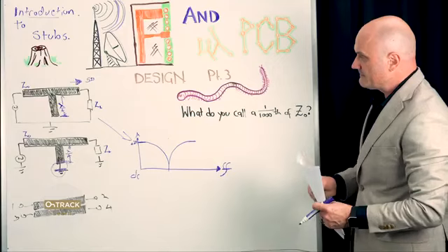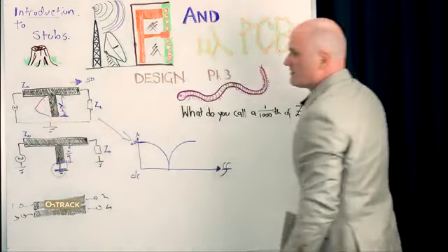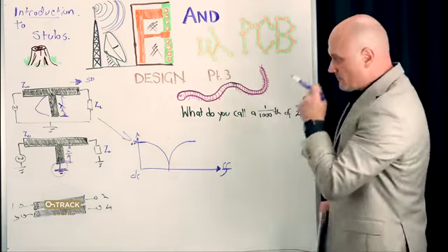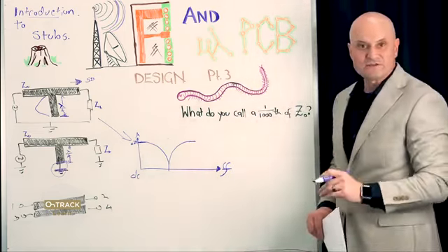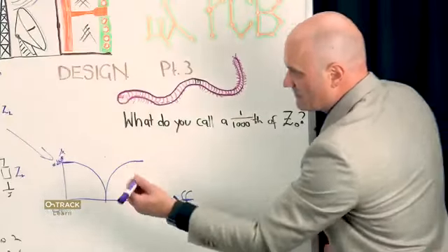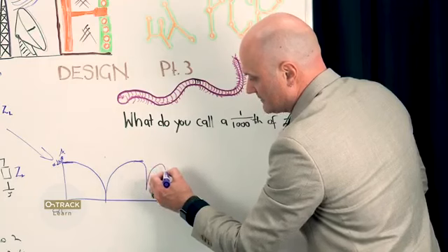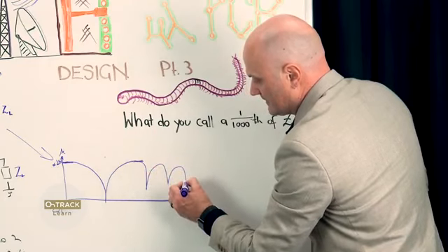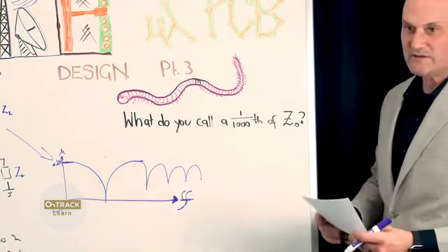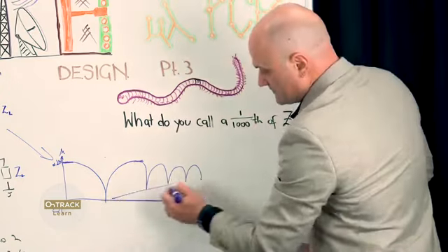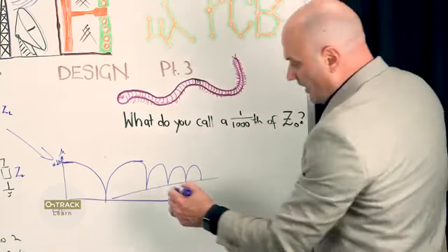It's a pretty pathetic analogy, I know, but it's the same kind of idea. And so here, when this is some multiple of quarter wavelengths, it's going to resonate and form that short circuit behavior. So what actually happens as you keep going up in frequency, you start to develop these repeating notches as you go higher and higher in frequency. And the depth of the notches usually in a practical circuit will decrease. But why is this?